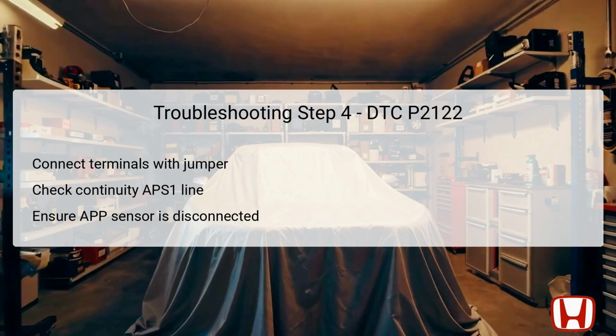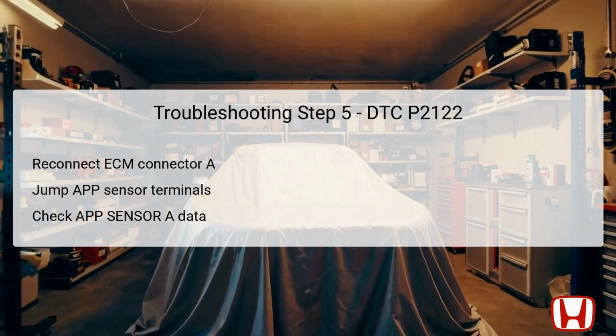Conduct this test while keeping the ignition in the lock position and ensuring that the APP sensor is still disconnected. If continuity is confirmed, the APS1 wire is good and you can move on to step 5. However, if continuity is absent, it indicates an open wire issue that must be repaired between the ECM and APP sensor. Step 5 is crucial as it involves examining the internal circuit of the ECM.